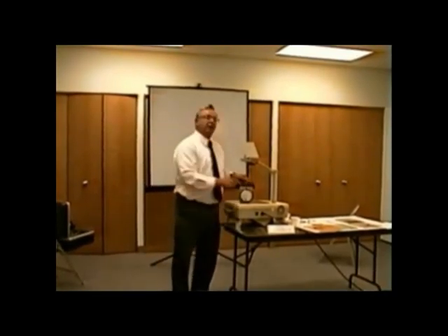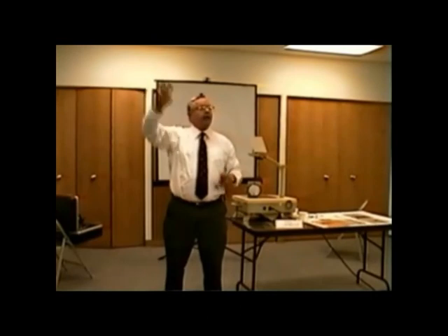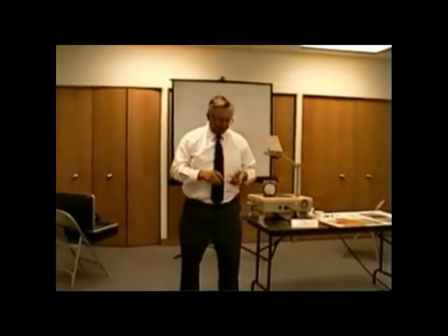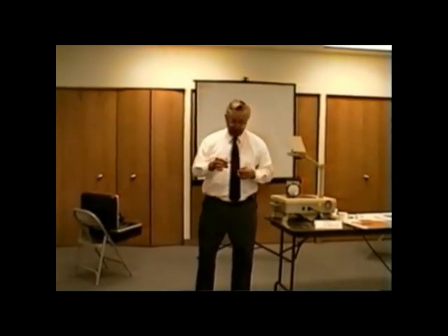And all we do is turn the blower on. That's it. And the needle's going to go up because whatever pressure, remember, static pressure means that the air that's being pushed produces pressure on the ductwork. It's measurable with an instrument, and we measure it in inches of water column. So it's a specification that we use in the industry. If we take a probe and a proper instrument and we stick it in the ductwork, we get a reading, and it's measurable in inches of water column.